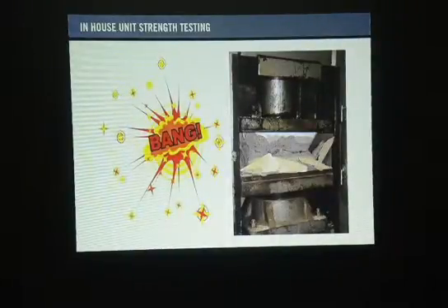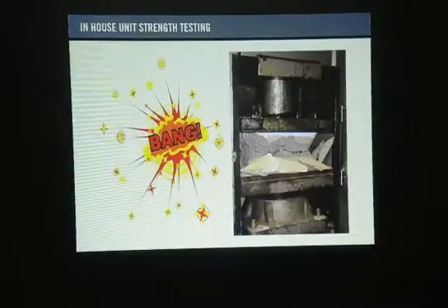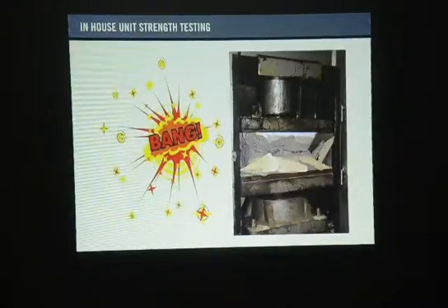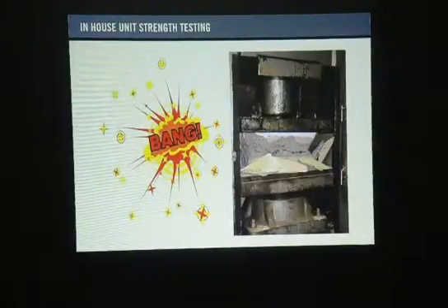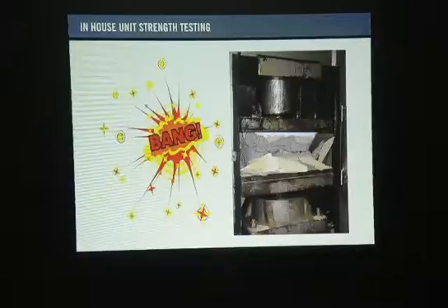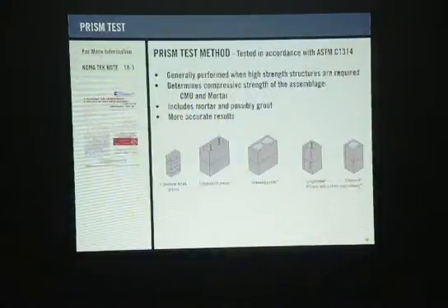When I worked for Hilti, I had a structural engineer and a civil engineer to work with. When we cranked an anchor, we wanted to see what the failure of that anchor in the concrete was going to be. And that's what gave us the tensile strength, okay? And then the shear value. Where did it shear, okay? They were all failures. That's where the number is actually recorded, is the failure.